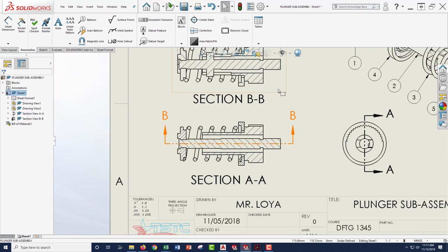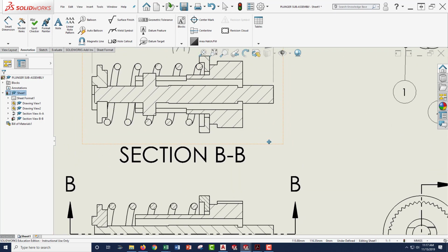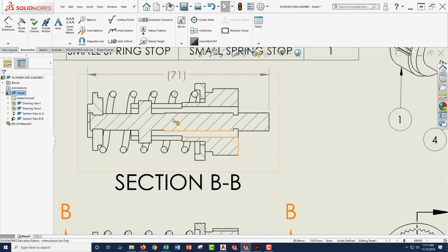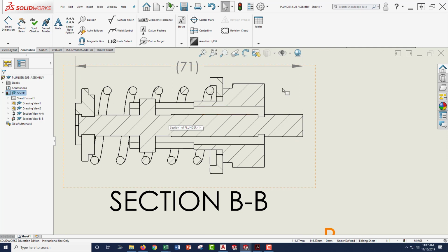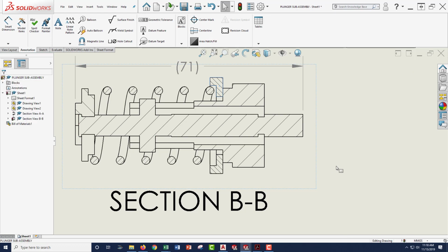All right. I need the same thing done to both. Actually, it's already occurred. Nice. Okay. I believe I remember this one being, I had selected auto hatching. So it did offset the adjacent parts accordingly, but we also need to go in there and increase the hatching visibility. Check mark. Looks like we're good.